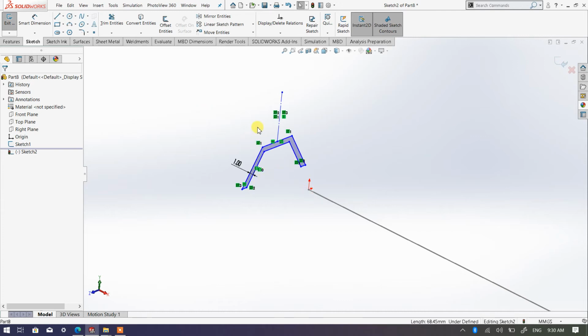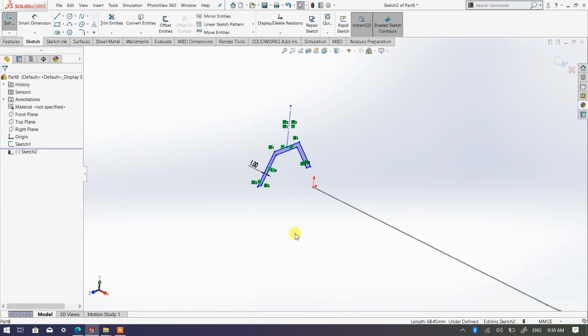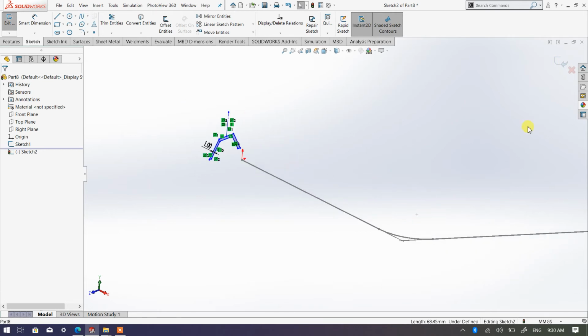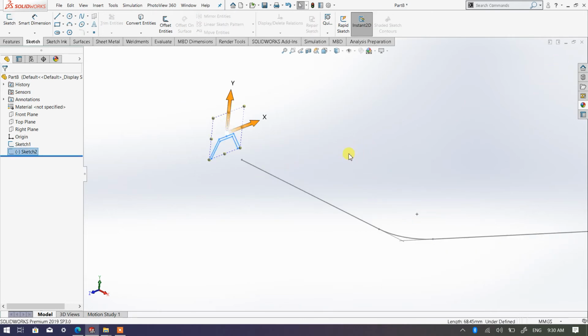Okay, you can put it somewhere here, or wherever you feel is a suitable place in order to form your 3D solid modeling part. All right. However, remember that the profile should be perpendicular. If you would like to create this profile, it's not necessary to start at this endpoint. However, the profile should be perpendicular to this particular path. So once you confirm, again, you need to exit from this sketch.